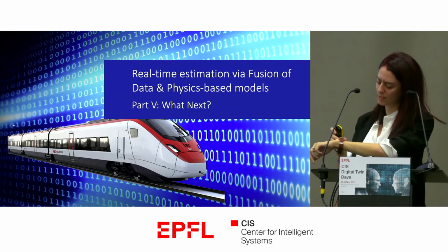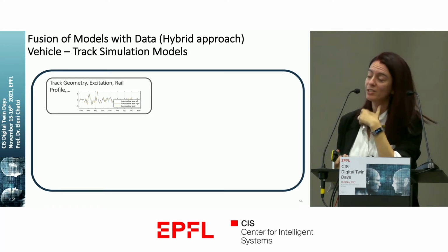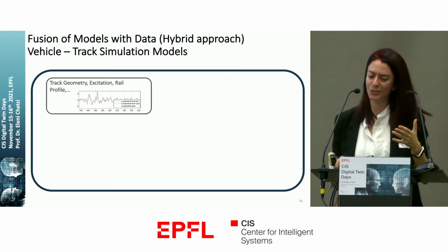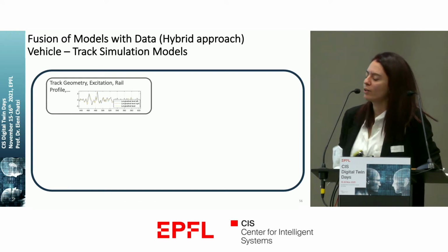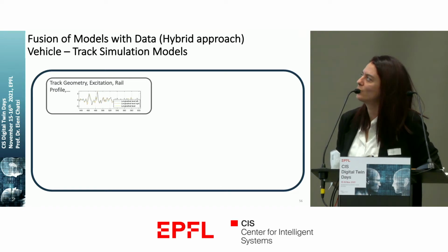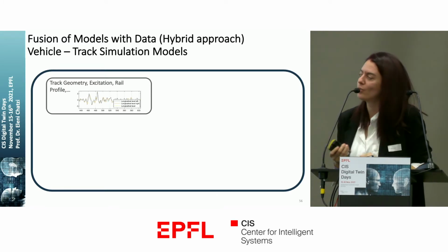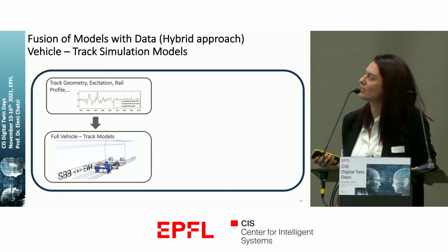And then just to end with this, I would like to show you what could be done next, because up to now I was trying to derive indicators of performance that stem from monitoring. One of the popular application areas for us, apart from the wind energy sector, is to do this on railway infrastructure, where, again, as I mentioned already, we have instrumented vehicles in collaboration with the Federal Roads Office that usually gives us information in the form of acceleration at the axle box of these vehicles.